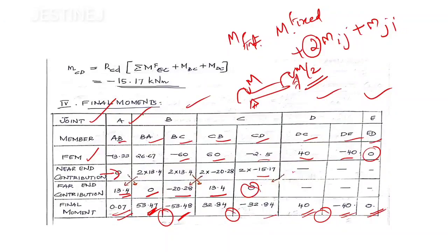With the help of these final moments you can easily draw the bending moment diagram, and after that you have to calculate the reactions, and with the help of the reactions draw the shear force diagram. I hope the section is clear, and with this we wind up today's session. So thank you.